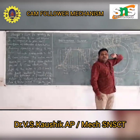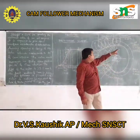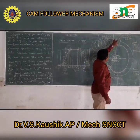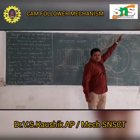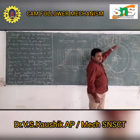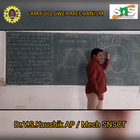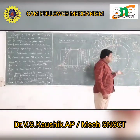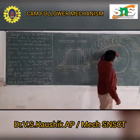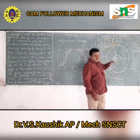We should set the compass to 20 mm, place the center point here, and draw the circle. That circle should touch this base circle. For the base circle to be engaged, we should draw another circle.